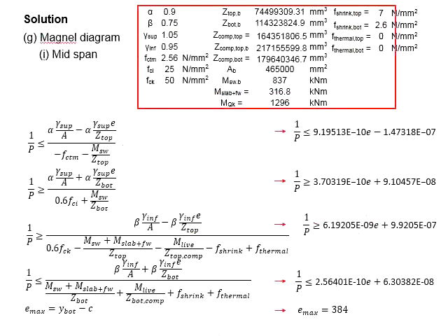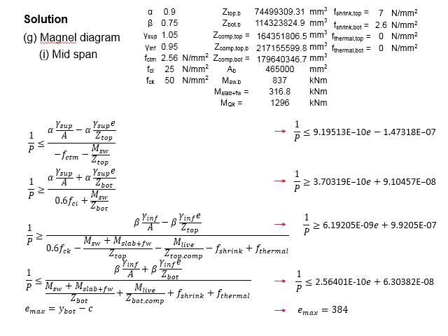Having all the values obtained, you have the factors obtained from the questions. The properties of the concrete is calculated in the previous calculations, and the section modulus is calculated from the geometrical properties at the early stage.